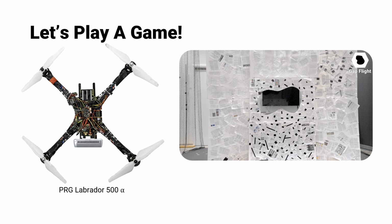So given that information, what do you think is the perception stack? You might say that you're doing the exact same thing from before, which is looking at parallax, and you would be 100% correct. But the way we do this is a little different. We detect the matching features between the two images, like we discussed. This term is called optical flow. But instead of computing the full optical flow, because it's computationally really expensive, we found a very nifty, parsimonious way that uses about an order of magnitude fewer resources. We call it the aleatoric uncertainty in this optical flow.